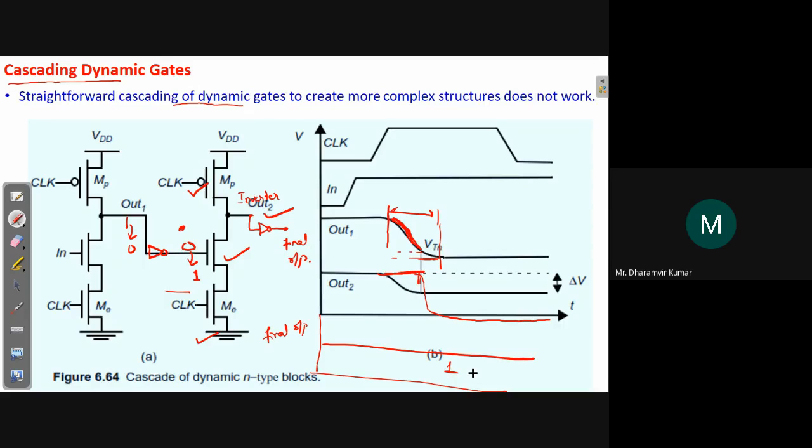Okay, so you will get the output in non-inverted form. Because this inverter has been introduced as a new element here, the outputs are available in non-inverted form, because earlier they were available in inverted form. Remember, when we have two transistors, this was not actually AND, this was the implementation of NAND. Now when we insert an inverter here, it becomes AND. So all the outputs are available, but in non-inverted form in domino logic.